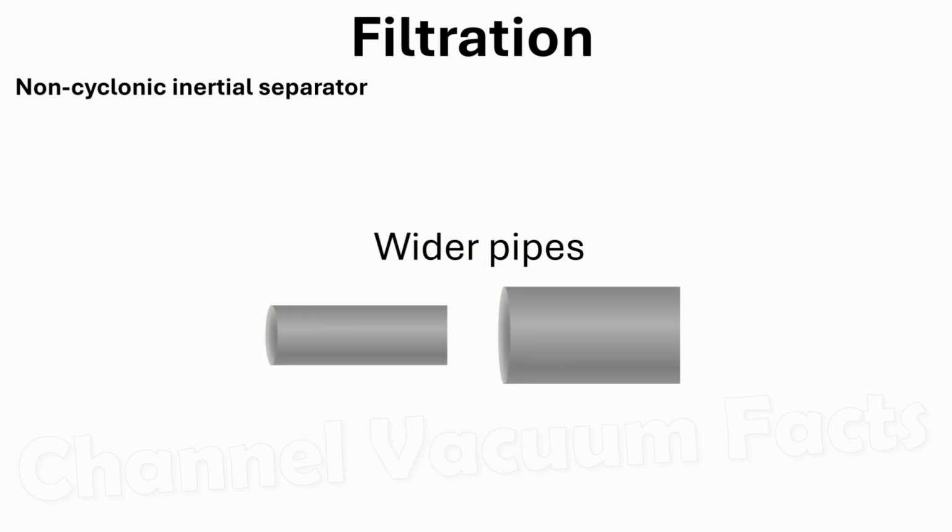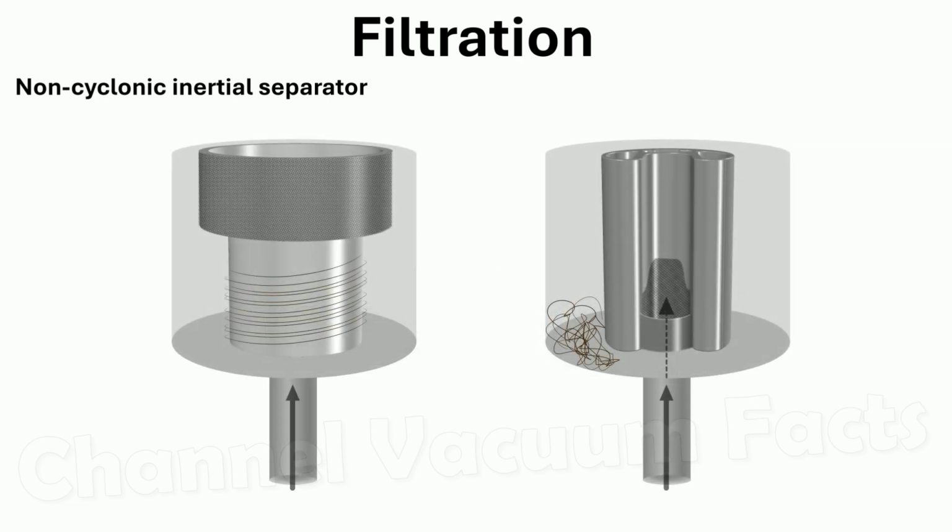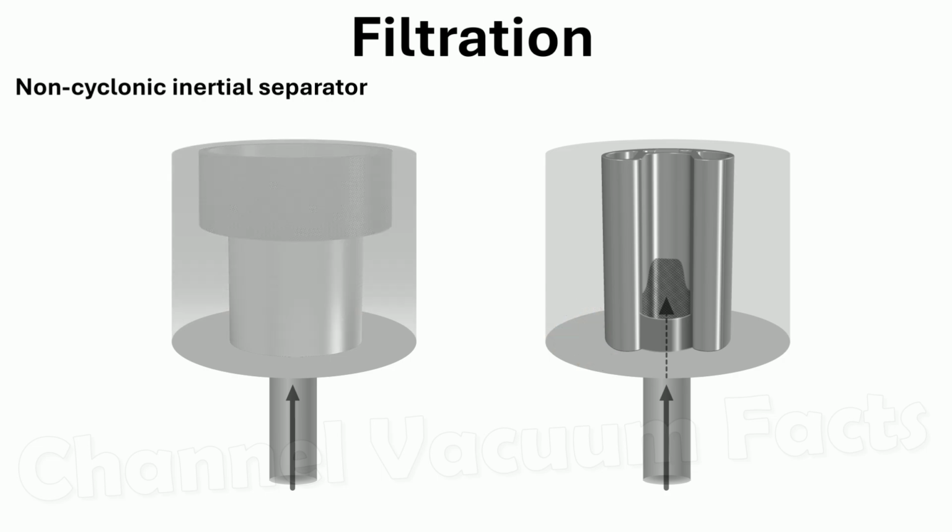Not needing to create an initial jet to spin around the bin allows for wider diameter tubes that help prevent blockages where larger particles are collected. There's no recirculating of airflow like with the current cyclonic and bin shroud design, which means long hair doesn't wrap around the centerpiece. This should also help avoid bin clouding caused by particles creating tiny scratches in the bin surface that scatters light.